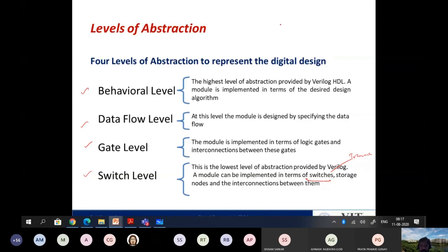By this time you might know from your digital IC course the basic inverter logic, right? So this is the transistor level design, and then I will use the PMOS keyword and NMOS keyword as available in Verilog, and then supply0 and supply1. Thereby I am able to model this using switch level code. It's the lowest level of abstraction.